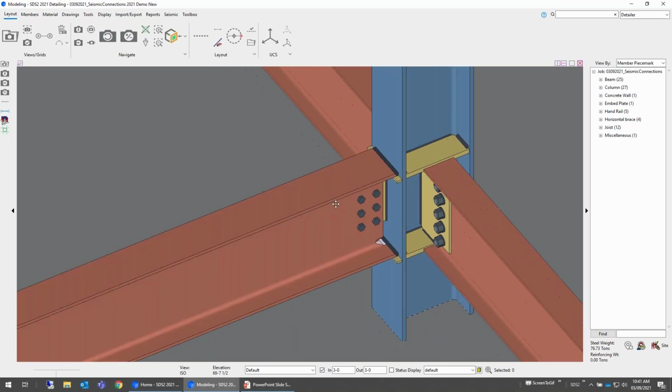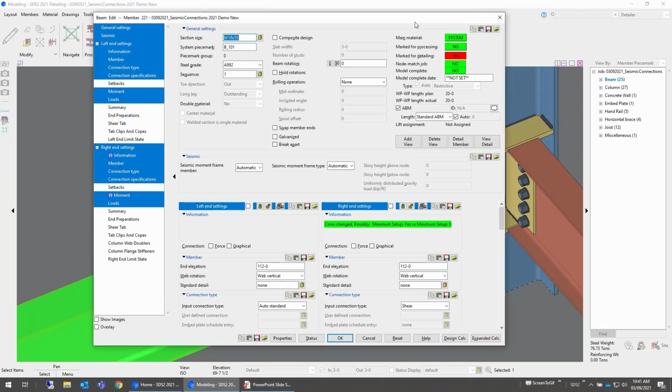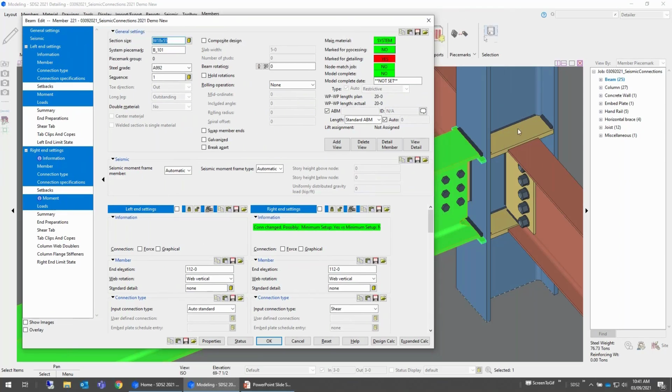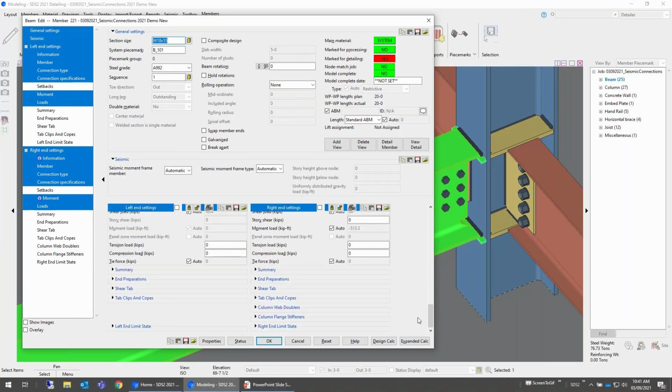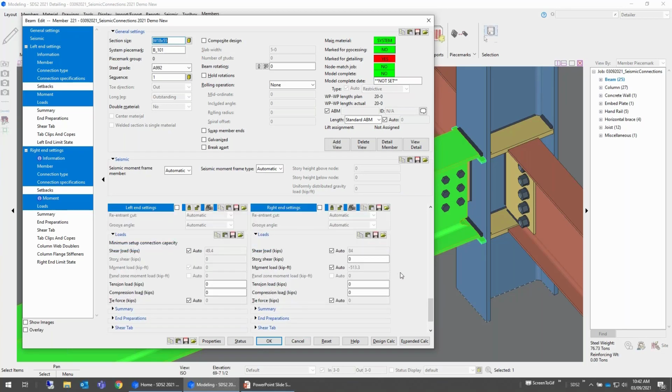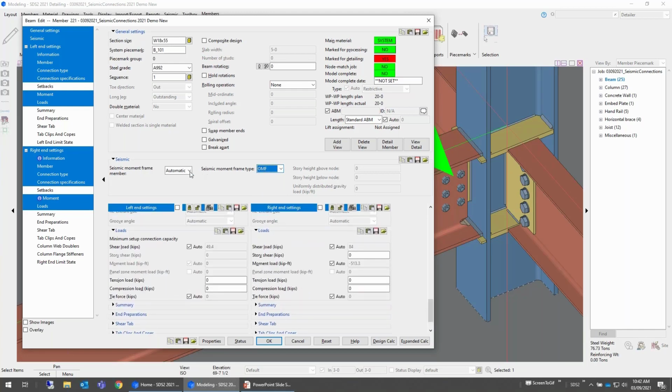Then we talked about the panel zone moment load that controls what the web doublers in that column are going to be designed based on. Excuse me, am I doing something wrong, Colin, here? Or is that only applied to the other moment frame types? No, that applies to OMF as well.